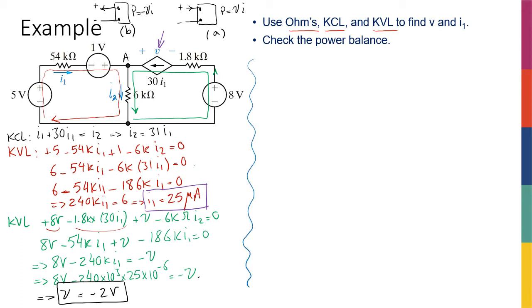Okay, so let's do this together. One thing that you should have figured out by now is that for a resistor, we know that P is equal to VI, right? But the nice thing about the resistor is that the V and I of a resistor are actually related to each other, unlike the voltage sources and current sources, whose voltage and current have no relationship with each other. For a resistor, we have Ohm's law. So instead of V, I can write Ri, and then if I keep the I, this is going to be Ri squared. And similarly, I could have replaced I with V divided by R, so this could have been V squared divided by R. Okay, so power of a resistor is basically Ri squared or V squared divided by R.